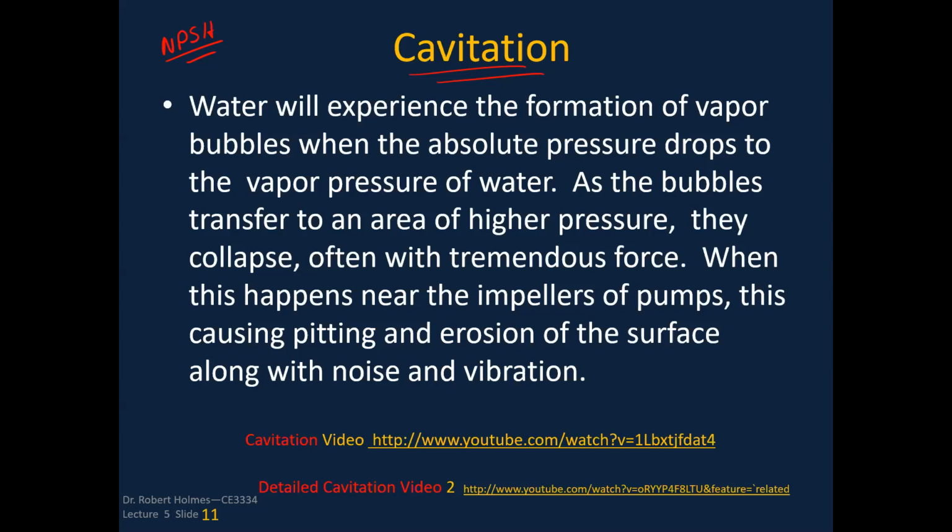That is not exactly the same thing as cavitation, because in cavitation we're not necessarily increasing the temperature. What we're doing is lowering the pressure. As the pressure lowers, if it gets down to near what we call the vaporization pressure, that fluid will create air bubbles. Pumps are really bad in this sense, because as the impeller is spinning, you get areas of extremely low pressure.